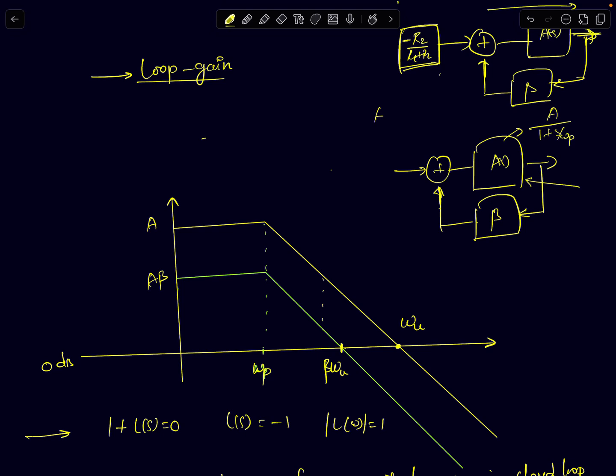So we discussed this procedure where we said we can arrive at the closed loop pole or the 3 dB bandwidth of an op-amp based circuit with a frequency independent feedback network, where your feedback factor beta doesn't depend upon frequency. So usually it's comprised of either resistors alone or capacitors only feedback networks. In such systems, we said that we can directly read the point at which the gain becomes unity and call it the 3 dB bandwidth or the pole of the system.